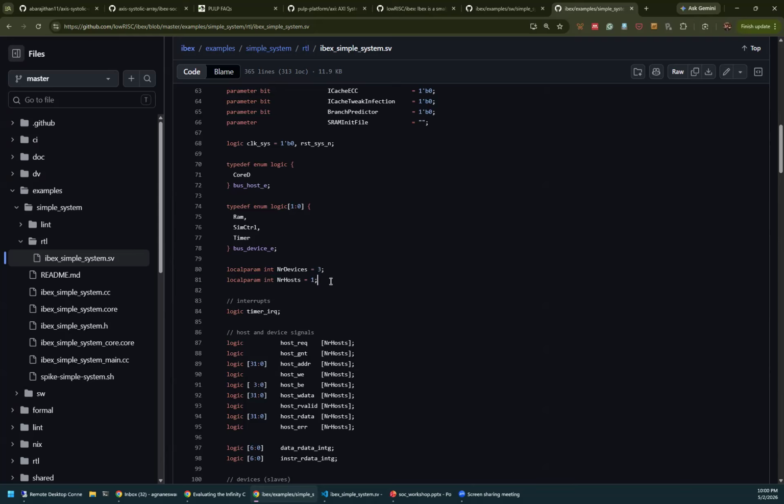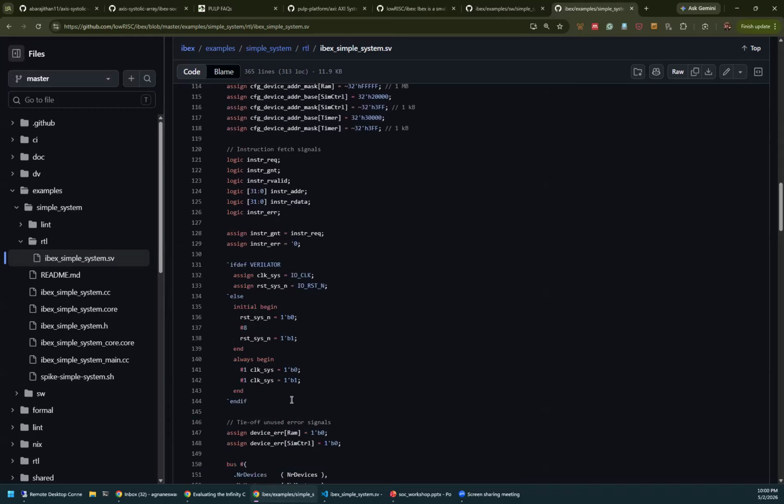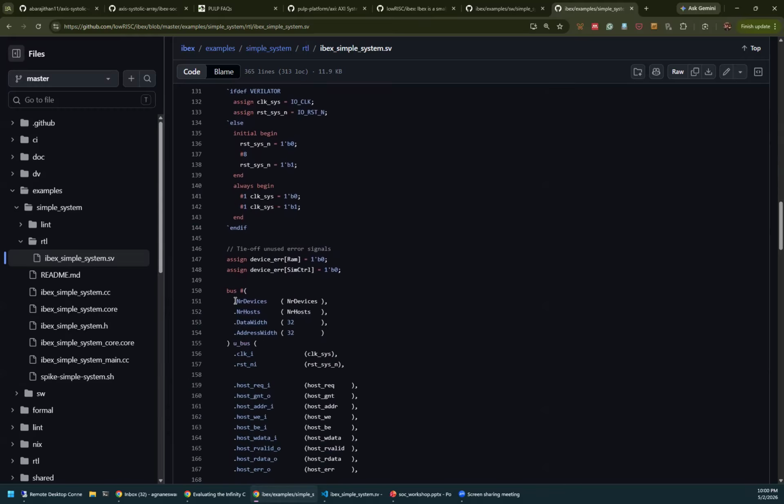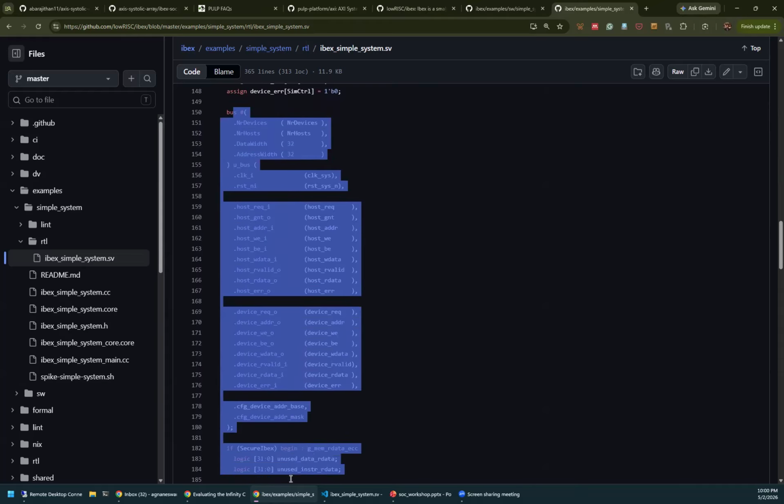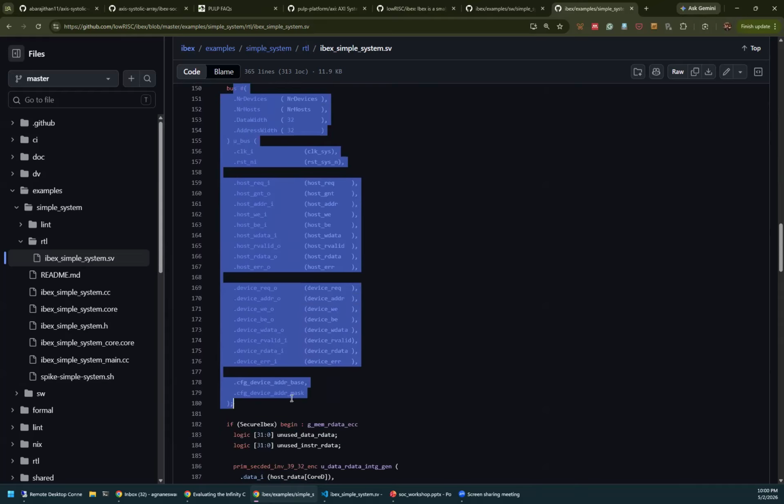But the way I thought about it is that the system here is very simple. When I was trying to integrate this, I had a bunch of issues. Then I looked into this bus protocol they have, and the actual bus module. This is a very simple bus, so it doesn't handle a lot of cases, right? I didn't want to put multiple masters that asynchronously keep talking back and forth. The bus can't handle all those collisions and everything.